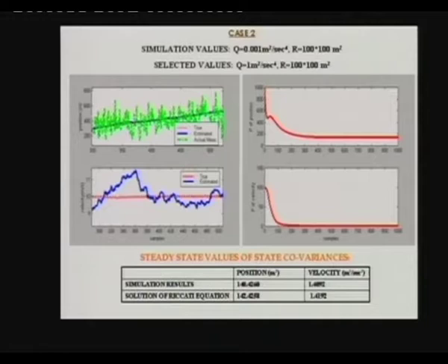See, the measurement data is not that different. Can you see that? The measurement data looks almost like the previous data. Why? Because the measurement data is position, so acceleration gets 2 times integrated. So every time you integrate, you are actually basically putting a 1 by omega gain, so power is sharply falling.